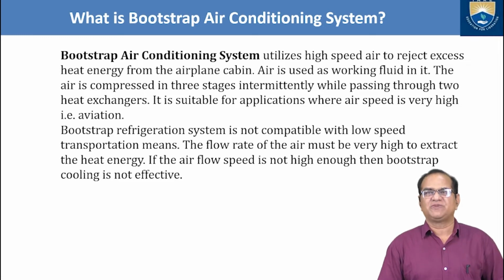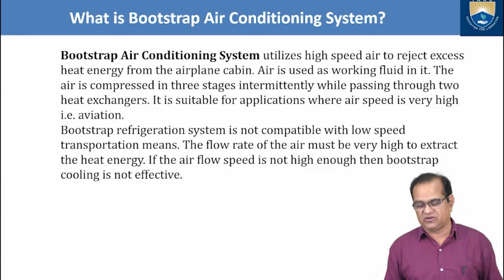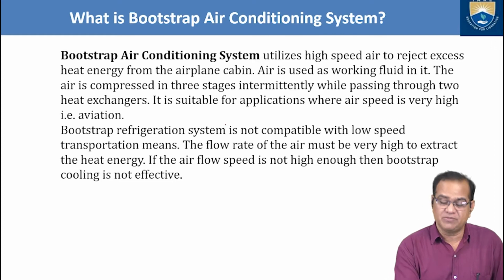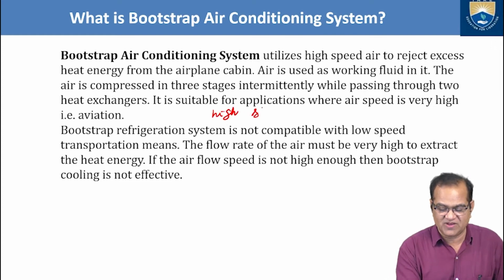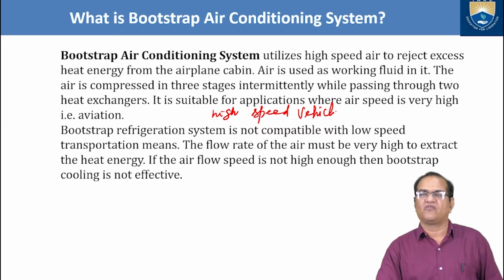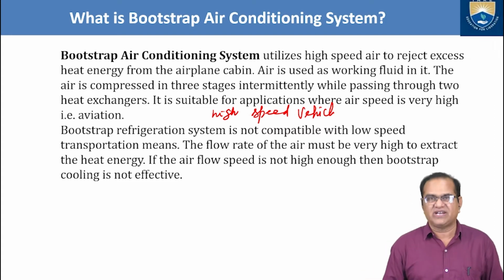If the airflow speed is not high enough, then bootstrap cooling is not effective. So that is one takeaway of this. This system can be used only for high speed flight, high speed vehicles like aircraft. It is not suitable for a ground vehicle. Okay, so that is the first.